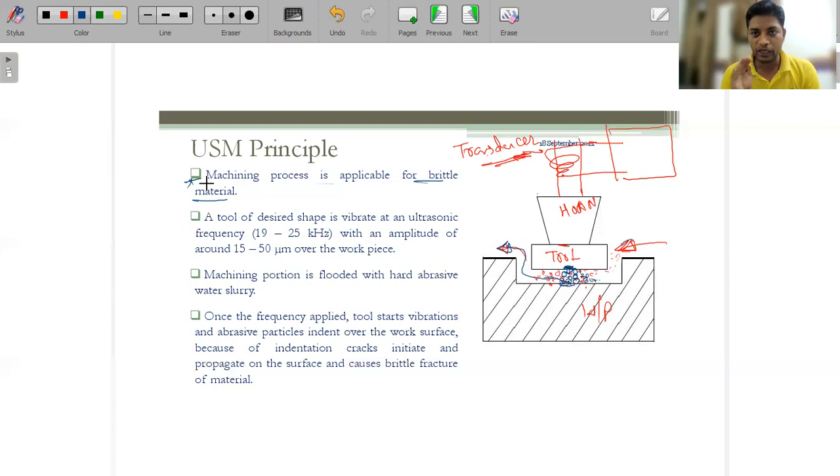Okay, and why I'm talking about emery paper is because this is a kind of vibration. Whatever we are rubbing over the workpiece surface creates some kind of vibrations, meaning some amplitude is there. These abrasive particles transfer vibrations from one to the second to the third one, to the workpiece, and it's a kind of scratch only. They are removing the material by this scratch.